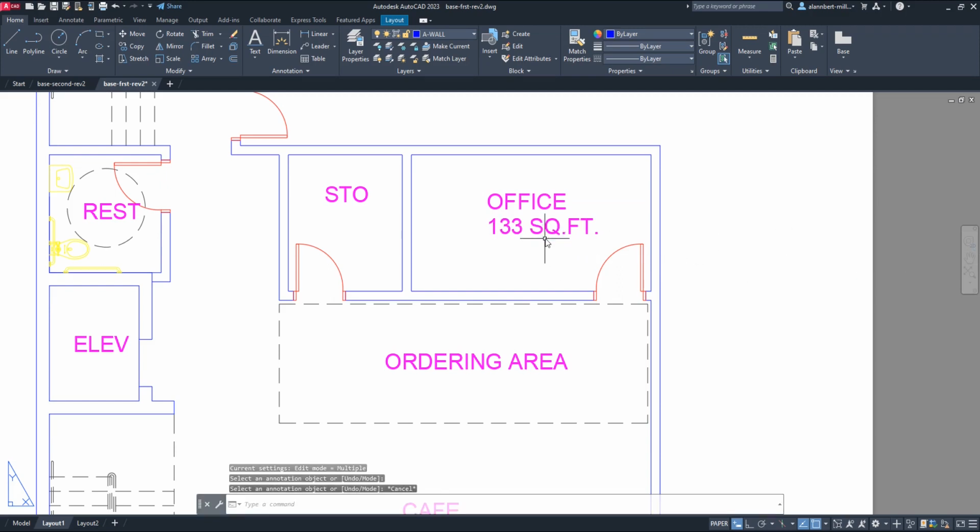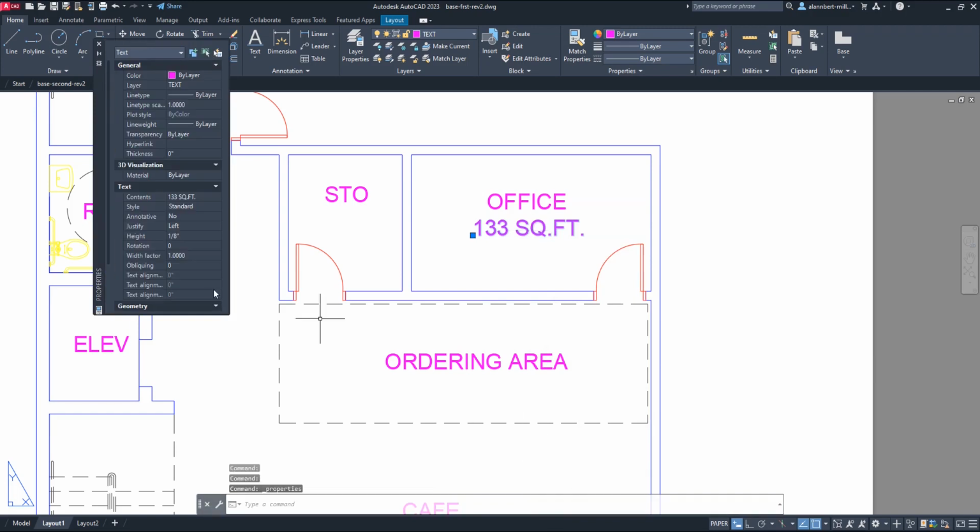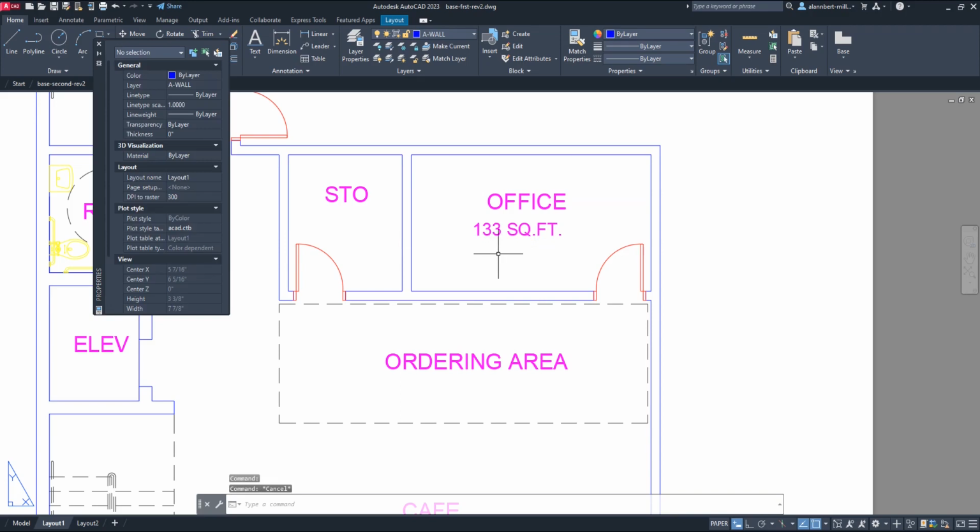Now, you may want this text to be a little bit smaller. So you can double click, right click, and then click properties, and then change that to 112. Okay, and then there you go. If 116 is too small, then 110. There you go. You can see the height is going in increments of the closest architectural size. Okay, and that's fine. It will just show that to you, but it will actually use the height that you specified.